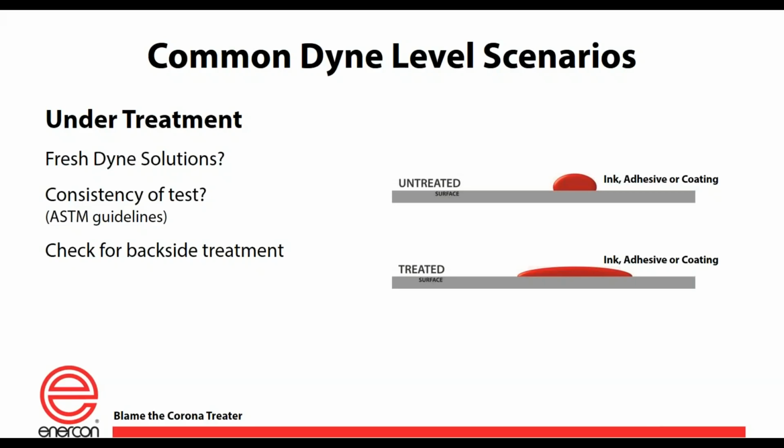Remember, the solutions are made up of 2 solvents, and the solvents will evaporate. So if you leave the cap off the bottle, you're going to now screw up the ratio of the 2 solvents that then equal a certain Dyne number. And as that happens, that Dyne solution now is not accurate. It's not valuable anymore, really. So if you are a little lax relative to storing and handling the Dyne solutions, you may want to change them more often than 6 months.